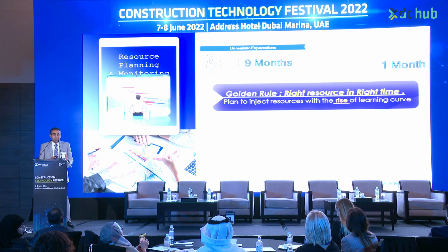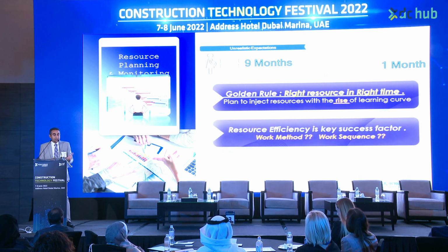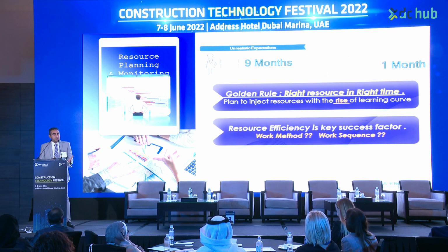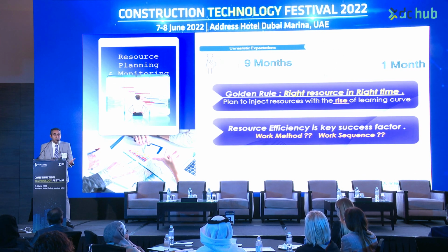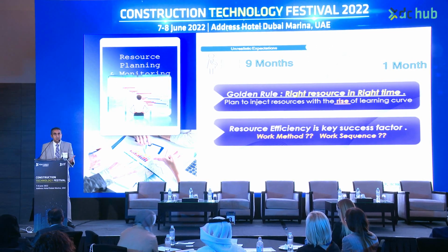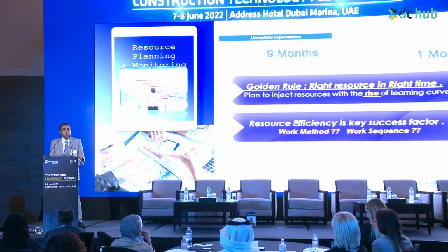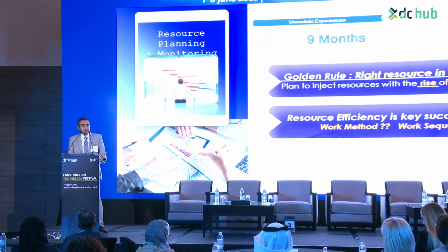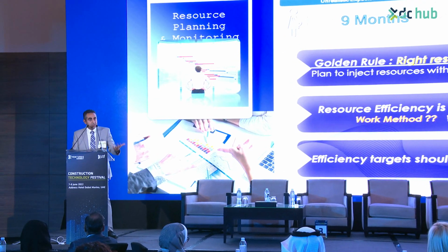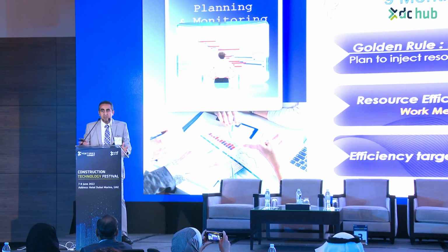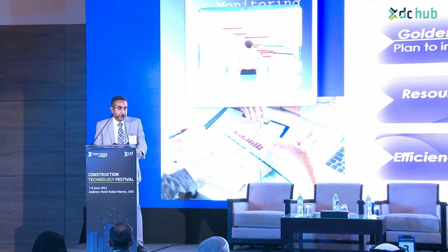We need to put the right resources at the right time, and the right time to inject resources is when our learning curve is increasing. If the resource efficiency is not really bringing what we are looking for, we need to question the method. Is it the right method or not? And we also need to question the sequence. Actually, prefabrication is a great advantage for shifting the sequence out of the critical path.